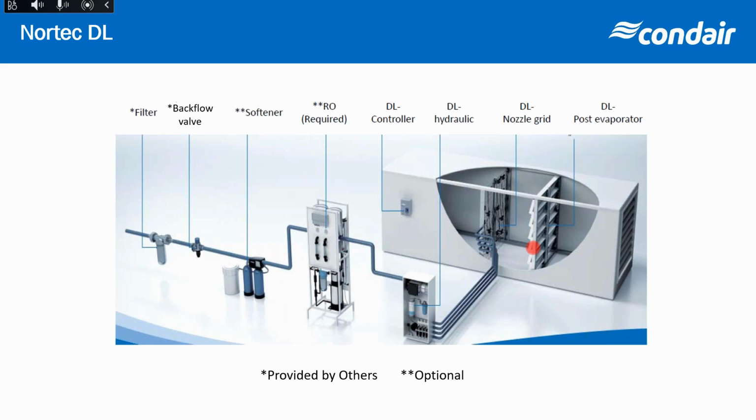As we're looking at the filter, we would bring in our potable water. We'd filter that water to remove the chlorine. From there, we would go into the softener. We would remove the scale, the calcium, and replace that with sodium. From there, we would go into our RO system, and we don't have a pump on there, but you will see the UV lighting. You'll see the control board. There is a storage tank that you can't see in the back there. And then of course, there's the RO membranes.